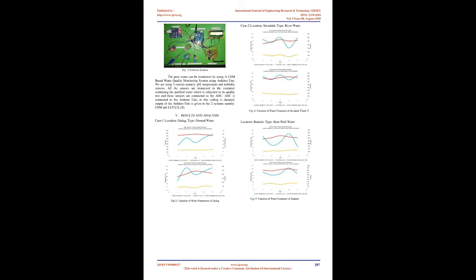Copper pipe is shown in the below figure. It is placed at the focal point of the parabolic collector. It is 45 mm from the base of the parabolic trough. Fig. 5 copper pipe/tube. Heat exchanger is shown in the below figure. It is made from 2-inch diameter PVC tubing and the length is around 22 inches. It converts hot water to normal cold water.